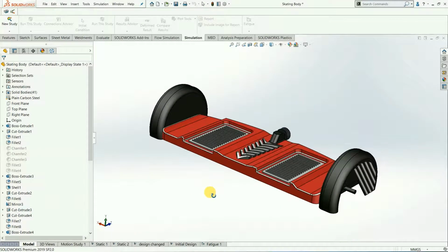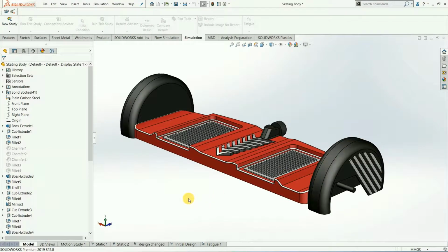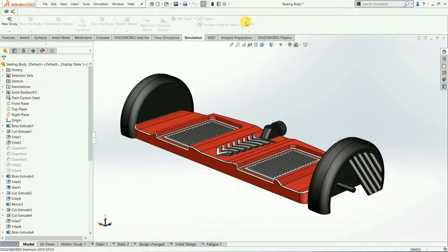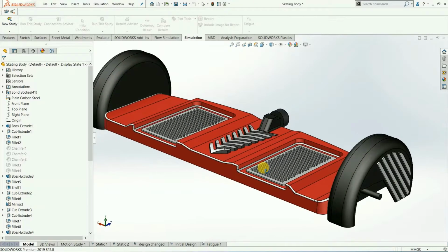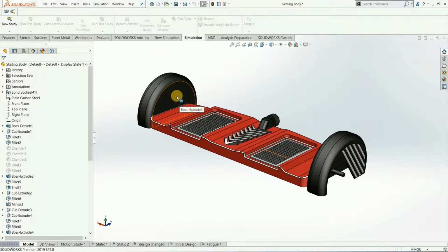We have taken the 3D model of the platform. The simulation strength analysis is also an add-on product to our existing 3D CAD. If you pick the add-on, it will generate a new tab, a new column or a control panel for this entire simulation. It will be plugged into our 3D CAD platform. For the sake of analysis, I need to simplify this model. So I need to remove the unneeded regions. I require only this platform.